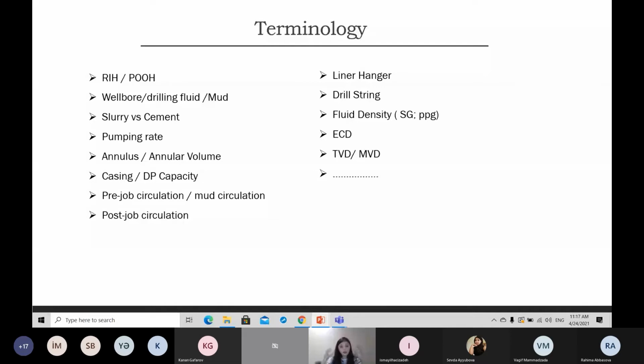We have a pressure generated from pumping in the bottom hole. When we use these depths and convert this pressure to one density, one weight, it will give us the equivalent circulating density. And it is usually higher than what we are pumping at surface.